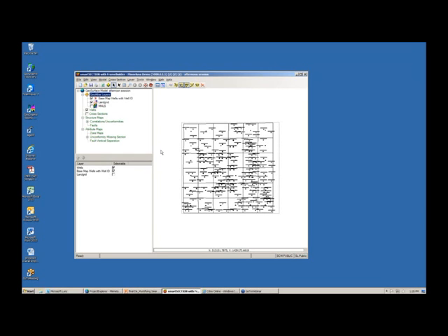But given that, it's common for people, particularly who are drilling horizontal wells, to have such an isomap grid that consists of data from seismic, from well base, and possibly from interwell points that they picked in smartSECTION. So just be aware out there, everybody, that's a very powerful feature of smartSECTION. You can use a surface that you've really tweaked, and you can use it to constrain others, particularly your drilling targets when you're going horizontal.